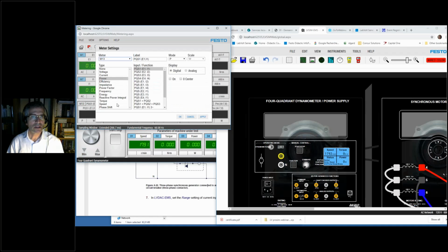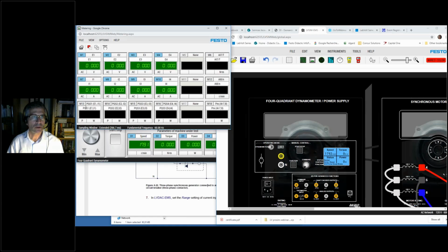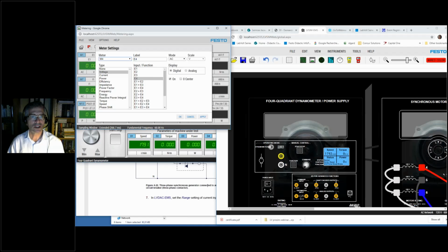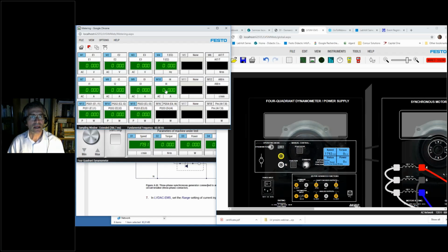And we will ask to see the active power on all three phases. And here I will check the frequency output of my generator, which is E2. So E2 is the voltmeter connected to the generator. And finally, here I might want to see also the reactive power.